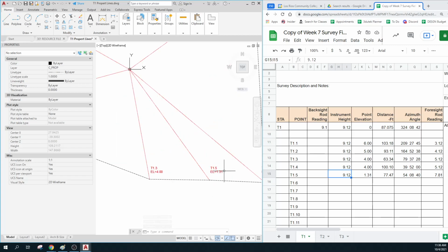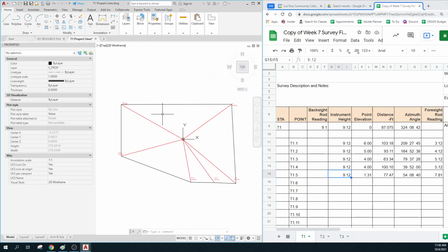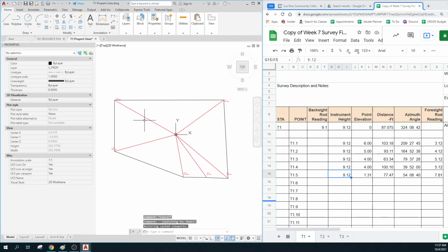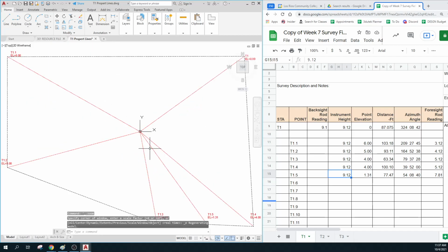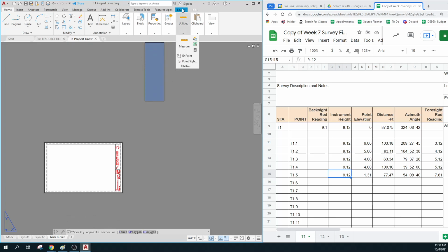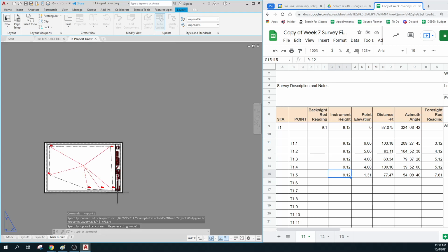Yep, but there it is. I've changed it around. I put the dip in here. I made this not perfectly straight, but that's pretty good. I mean, I was reading those readings, and they came out pretty close. So now let's go back over to here. First thing I need to do is close up my properties, double click so I'm fully scaled here. And that way when I come over here and put myself on my def points layer and go layout tool, rectangular, I'm going to get a good sized drawing here.